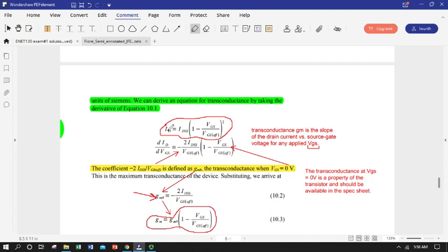So here's the drain current for any gate to source applied voltage in terms of max drain current, and gate to source voltage to totally cut off the drain current. And here's the slope of this drain current to gate source voltage function in terms of all the same stuff, but instead of max current we've got that slope under those same conditions. So this is the slope under the same conditions that apply the maximum.